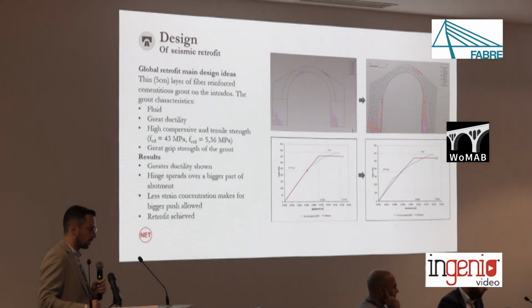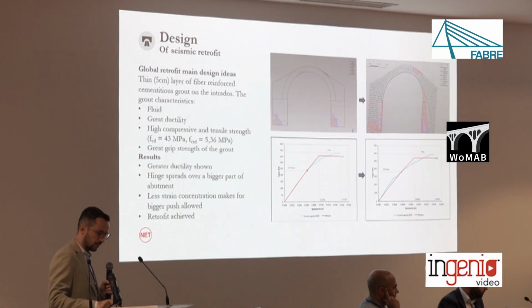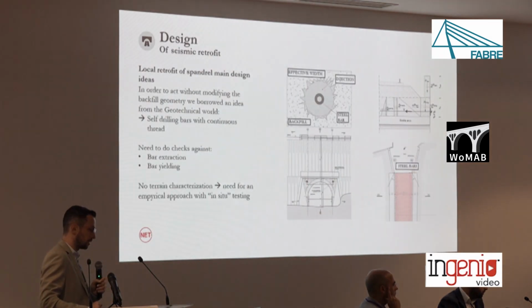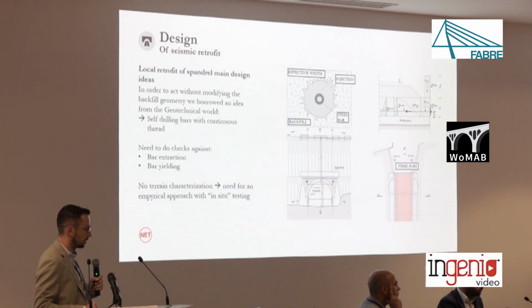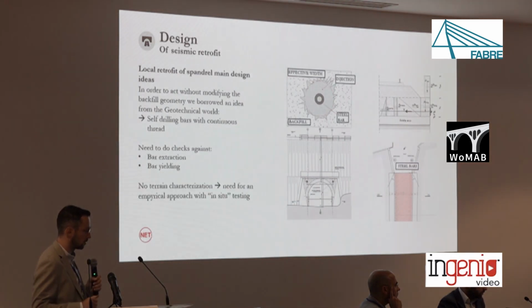For the local spandrel, again, being the bridge very wide and with a great part of terrain standing on top of it, the backfill being huge, we couldn't do the classic solution, which is basically a chain going from one side to the other of the bridge.